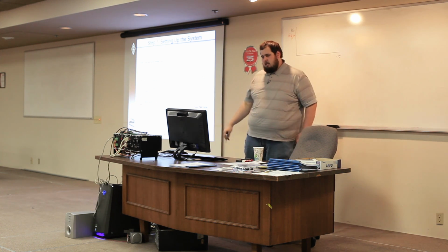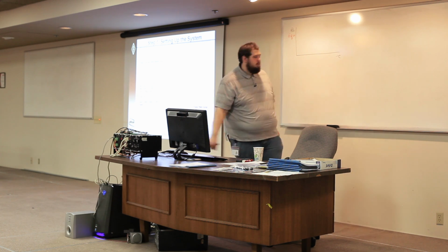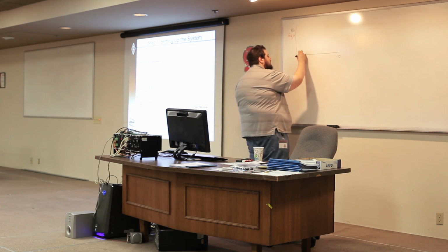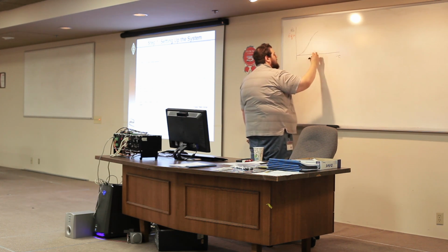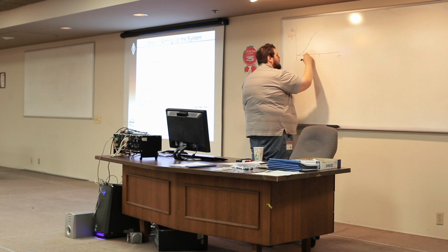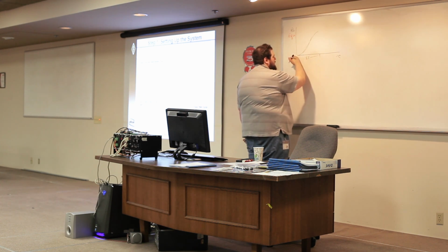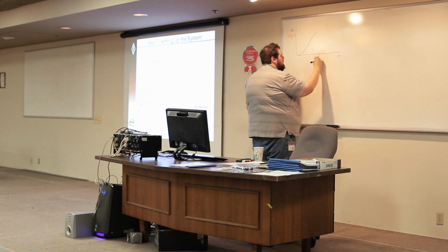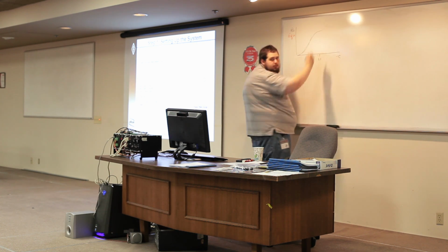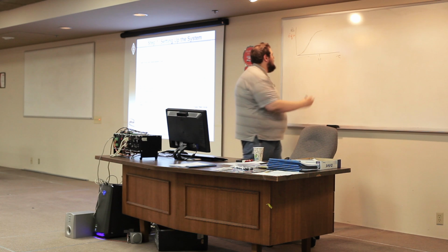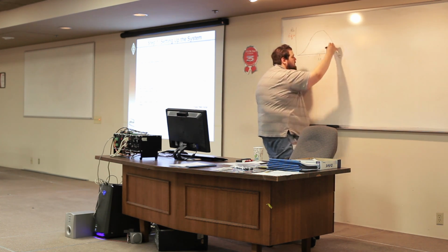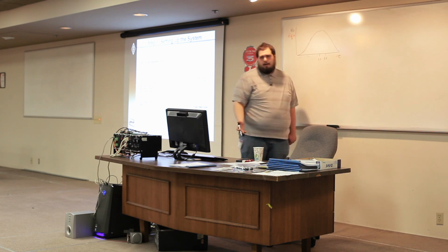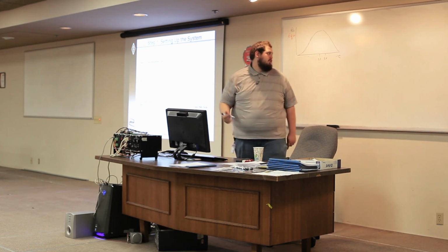We should expect TM is 5,000, TA is 100, so a move time of 5.1 seconds. Then it will stay there for a dwell of 500, 5.6 seconds, and then come down at another 5.1 seconds, so 10.7 seconds.